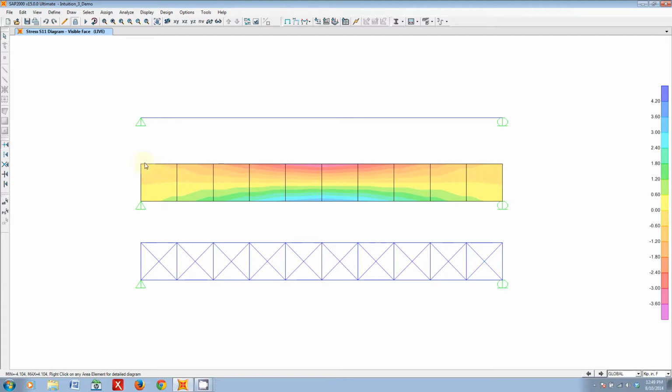But at the extreme top and bottom fibers of the beam, we increase in compressive stress to a maximum right at the top. And on the bottom tensile fibers of the beam, we increase to a maximum tensile stress at the bottom of the beam. And it's a linear transition between compressive stress at the top down to tensile stress at the bottom of the beam.